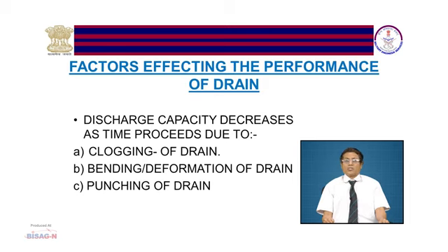Now, the third one is punching of the drain. Due to the lateral earth pressure, there may be a possibility of punching of the drain, just because the filter media can pass into this synthetic core drain in a punching manner.